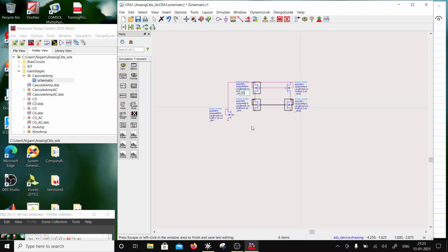So this is just a 20, and this one is going to be, no, I'm doing something wrong here. So this is a 1:10 current mirror, right? And let me just do the connections here. So this one goes here, and this one comes to this node, and out of this, so this is 1/4 the size of these two, right?